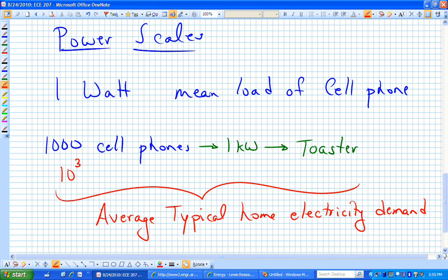Well, this is not energy, is it? Good question. The question was, 1 kilowatt for what length of time? We're saying this is the average load. It consumes 1 kilowatt of power. So if you want to know the energy, then you define the time, and then you integrate that 1 kilowatt average, which we're assuming is flat, for the length of time. So in an hour, you have 1 kilowatt hour. If you now get billed for that 1 kilowatt hour, in round numbers, that might be a dime. 10 cents is what you pay the electric company for 1 kilowatt for 1 hour.